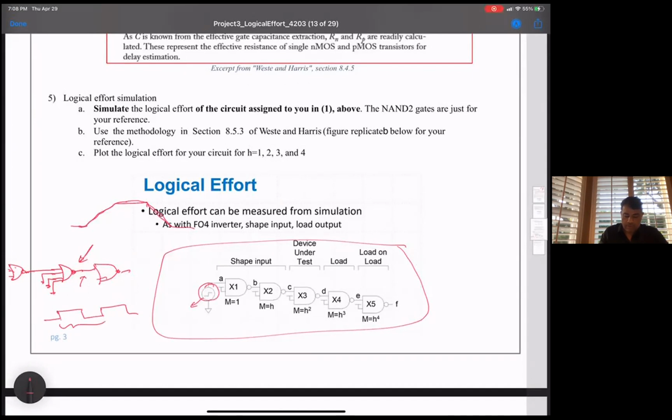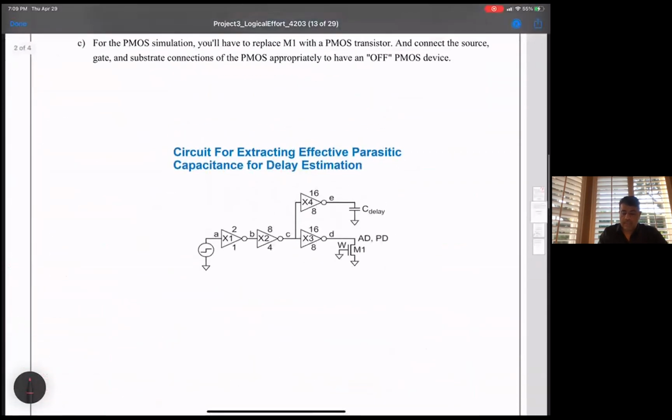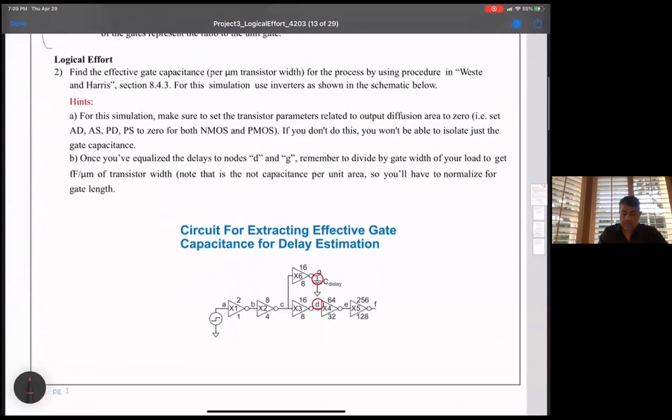So the output will just kind of start doing this. You'll get your output swinging by a few hundred millivolts, or otherwise just not swinging full rail to rail. So it's a pretty easy solution. You just have to slow the period down enough that you'll get your full rail to rail swing. So just make sure you do that. And if that doesn't work, it means you've got some other problem. So always make sure when you're doing this that you're getting full rail to rail swings.